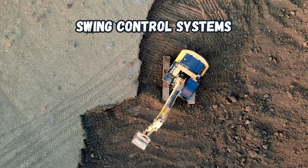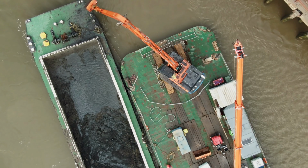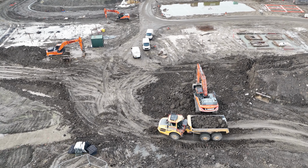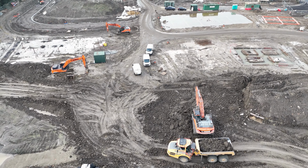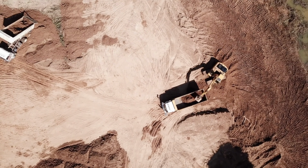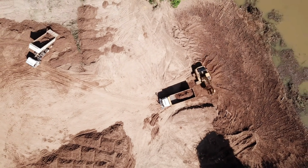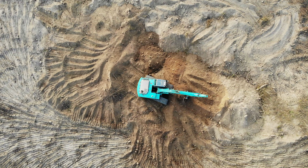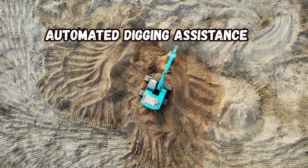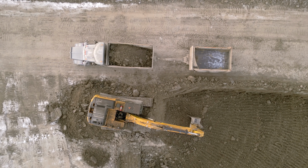Similarly, swing control systems regulate the acceleration and deceleration of the upper structure during rotational motion. By controlling the hydraulic flow to the swing motor, these systems reduce sudden starts and stops that could otherwise generate large inertial forces. This not only improves operator comfort, but also reduces mechanical stress on components such as the slew bearing and swing gearbox. Another emerging capability is automated digging assistance, which uses sensor feedback and control algorithms to optimize